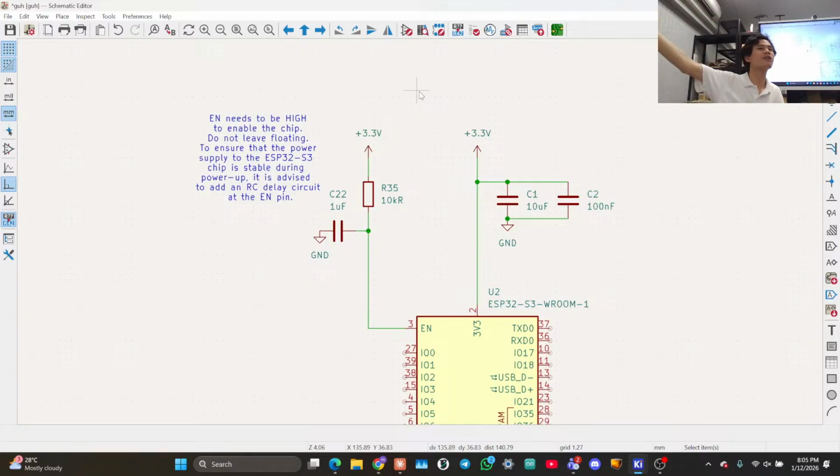Because now he's added ground to both sides of the battery. So this is basically connected already. This is basically connected. It's the same thing. Ground is a net, right? So everything in ground is shorted together by ideal wires. Yeah, so you shorted the battery. Basically, everything that's ground is connected together, and everything that's 3.3 volts is also connected together. Yeah, that's how it works.